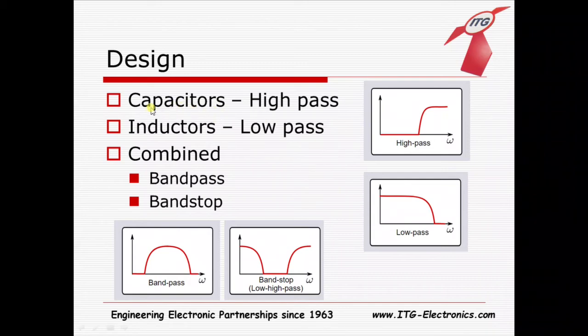So if you think about the capacitor formula that we looked at in the last slide, the higher the frequency, the lower the impedance. So down here in low frequency, we have very high impedance. This is flatlined. It's basically being reduced to nothing, no signal. Very good filter. Then up here in the high frequency, it's basically the opposite. It's being reduced to zero attenuation. It's all the way up here at the maximum signal. So this would be very poor if this area is what we were trying to filter out.